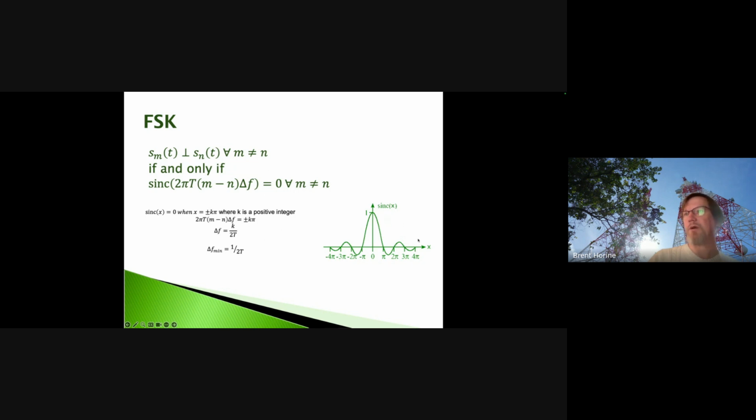And if we draw this sinc x type function out, we see that when the argument is an integer multiple of pi, it's going through 0. Halfway in between those steps, along with that 0, there's kind of a maximum value, right?